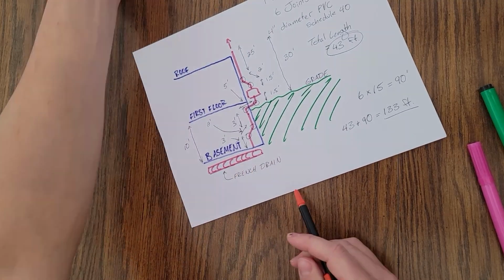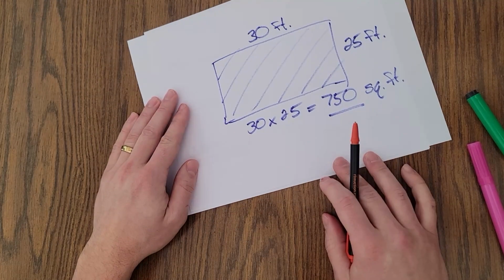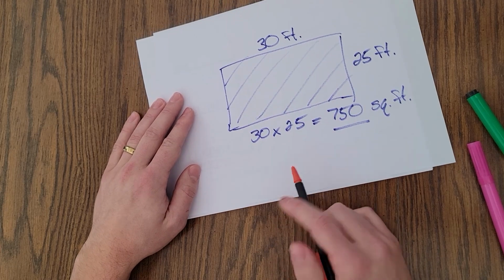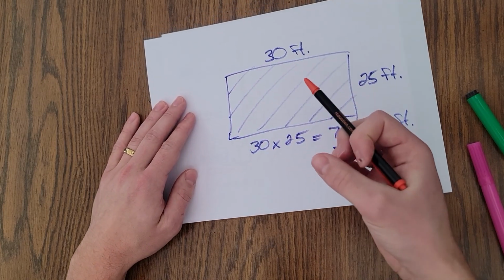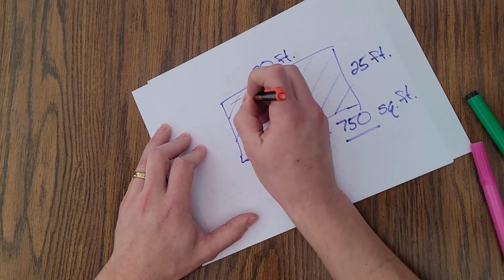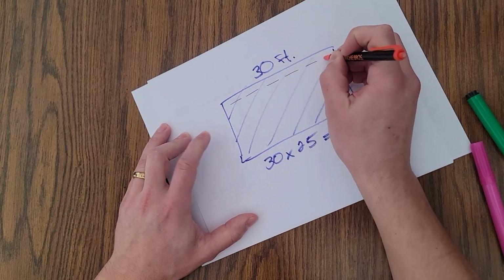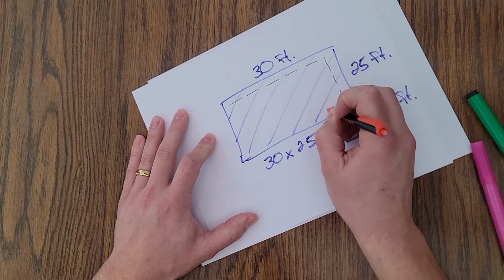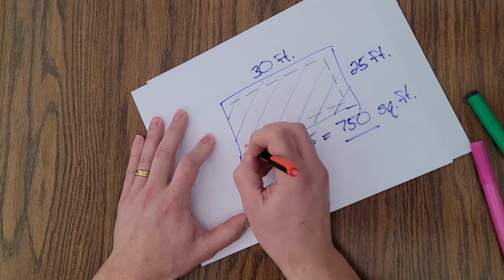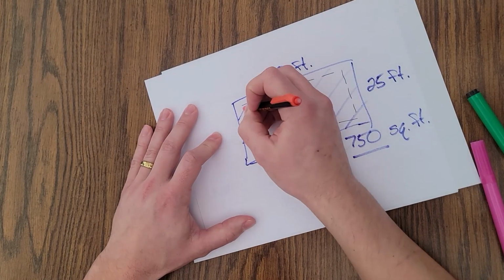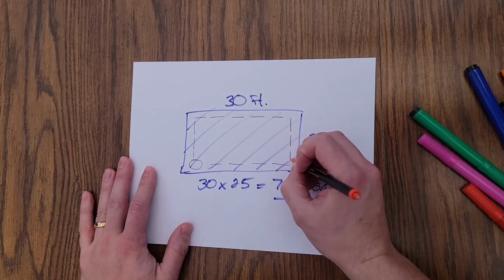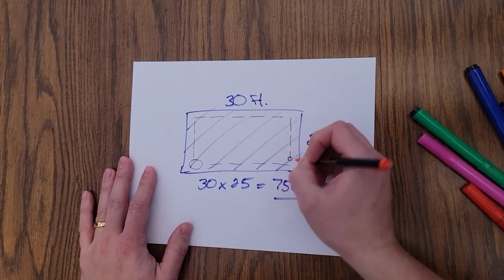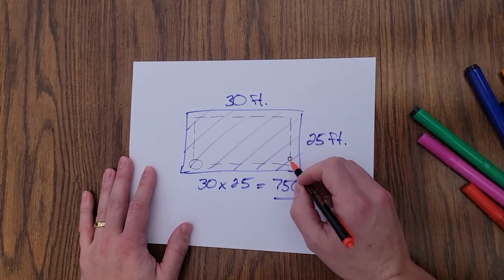Now, what we also have to include in our system is the amount of piping we have under the slab. So if we go back to the footprint of the basement, we have piping that runs all along the perimeter of the basement, something similar to this. Goes along the exterior walls, and then it goes to the sump pit that's in the corner. And then over in this corner here, I'm going to have the drop for the radon system go through the floor.